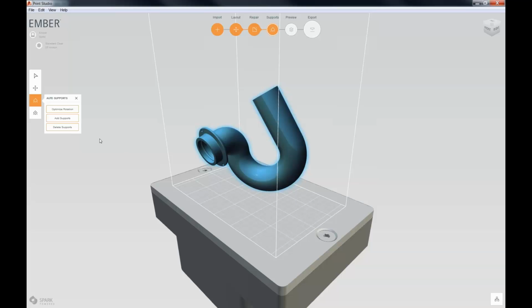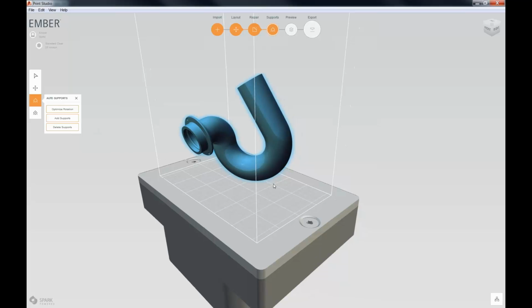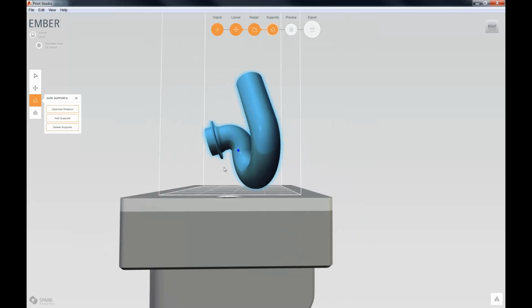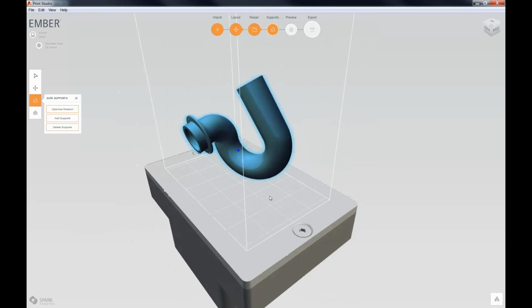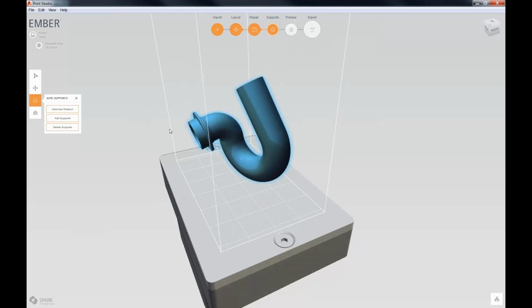Some general practices around 3D printing, such as overhangs, angle of slope, and the need for adding support. So it's actually oriented the component in this position for us, believing that that's the best print orientation. Now the problem is it's not going to print like that. It's not stable enough. So we need to add supports to stabilize the component and allow it to print any overhangs that the component has. So if I click Add Supports, you'll see that, and this process can take a few moments to happen, but it will automatically go and add those supports for us.